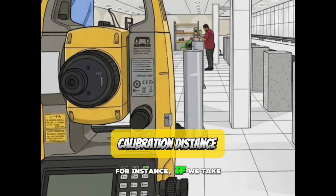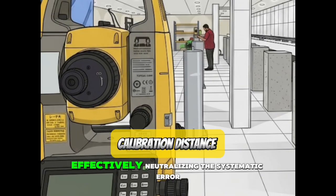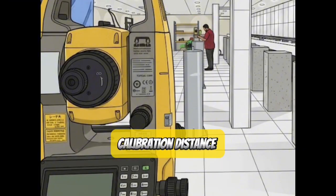For instance, if we take a total station to a certified electronic distance measurement baseline and its laser consistently reads 2 millimeters long over a known distance, we have successfully identified a systematic instrument constant bias. Through routine baseline calibration and software configuration, we can program the instrument to automatically subtract that exact bias from every future shot, effectively neutralizing the systematic error before it can corrupt our survey network.